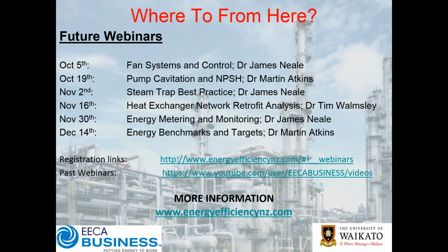If you have a fan from a reputable supplier, on the nameplate, in addition to the motor rating and the nameplate rating of the fan in terms of pressure and flow, it should have a rated fan speed for that nominal output, and as a separate item on the nameplate it should have a maximum recommended rotor speed. Now, it is fair to say that in certain situations that maximum rotor speed or impeller speed could be increased on inspection of the impeller.